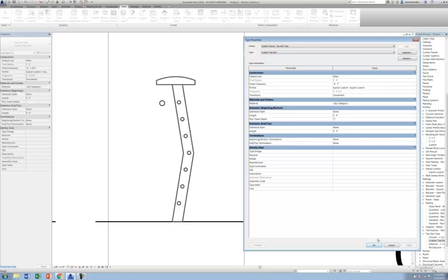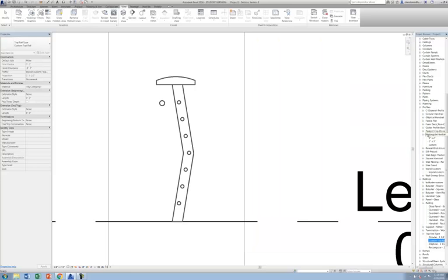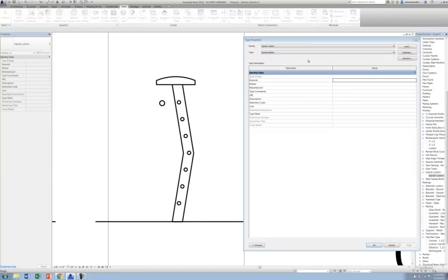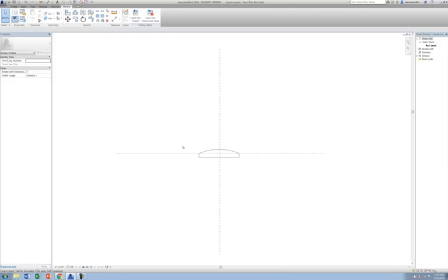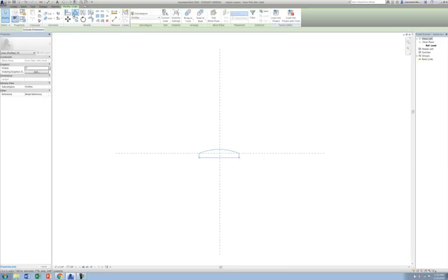And again, that's pretty big. I might go in and edit that profile. Again, at the next level, you can always come back in here and open up your profile. So if I think I've still got it open here, top rail custom. And if I just want to scale it down, I can hit the scale button.